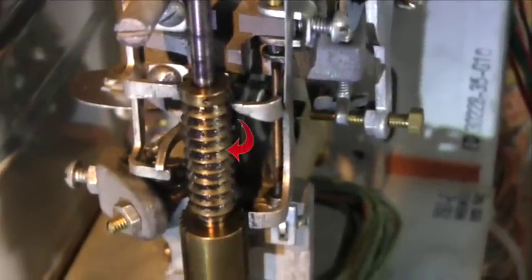This is the vertical ratchet. It is attached to the shaft and so moves up and down and rotates with the shaft. It provides the 10 teeth required for vertical stepping. Each tooth corresponds to one level in the bank assembly. The teeth are engaged by a vertical pawl that pushes the ratchet upwards by one step per engagement. Each step raises the shaft an amount equal to the distance between two bank levels.